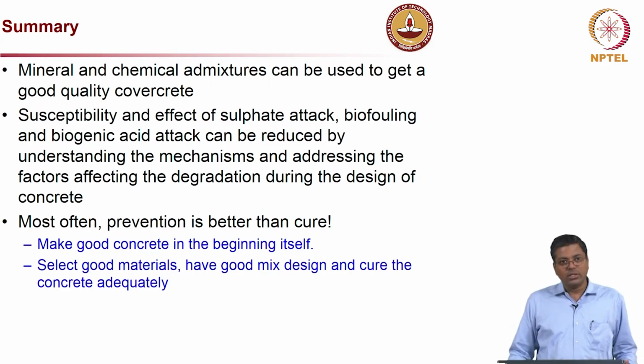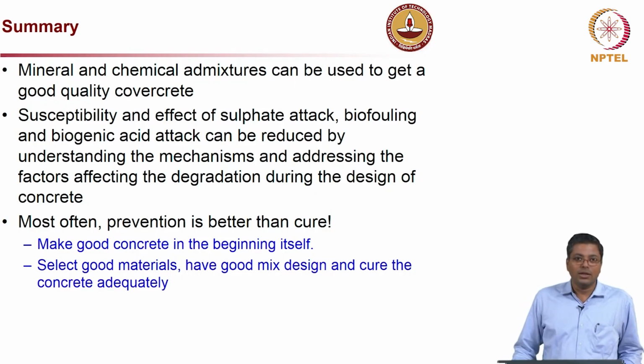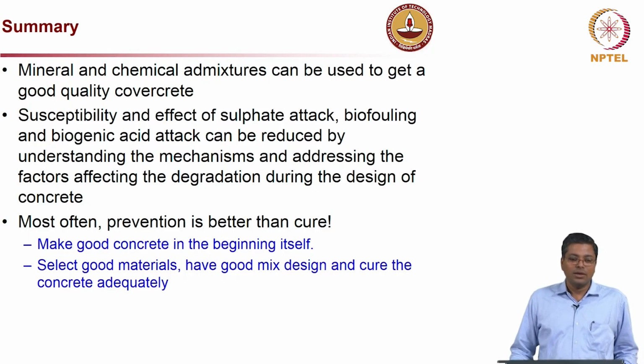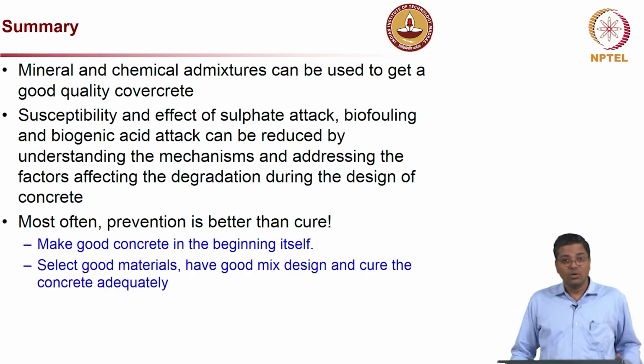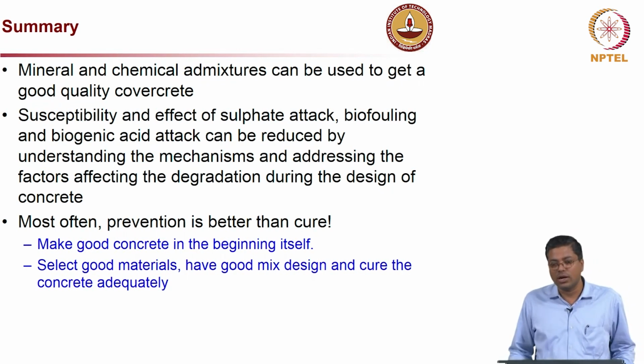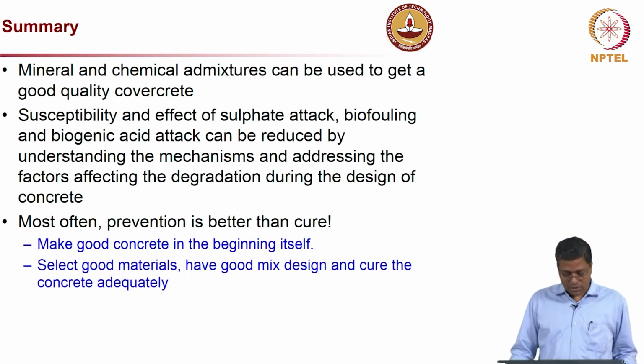And as we always say, prevention is better than cure. So, the idea should be to make good concrete at the beginning itself, and for that we have to select good materials, have good mix design, good placing procedures, compaction, and then cure the concrete adequately. All these are very much necessary, and if we do all this we will definitely have long lasting, beautiful concrete structures.